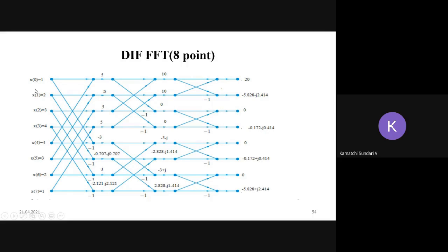And you have to remember, while supplying our input data to DIF FFT, the input should be in the regular order. Whatever order we are having at our inputs, given input, that is in our question paper, in our example input signal, that should be taken in the same way. So x of 0, x of 1, x of 2, x of 3. In the ascending order, we have to take our input signal.